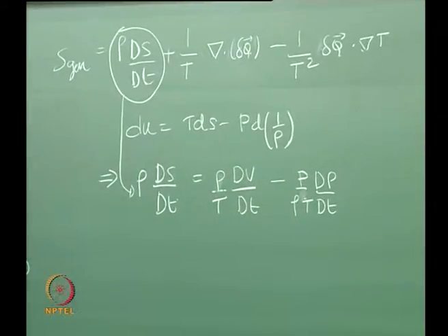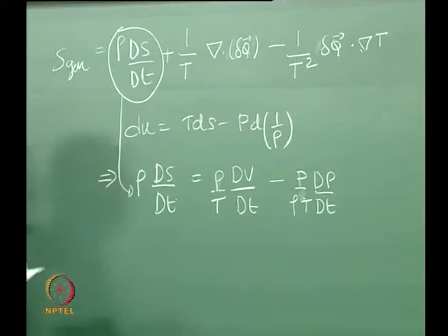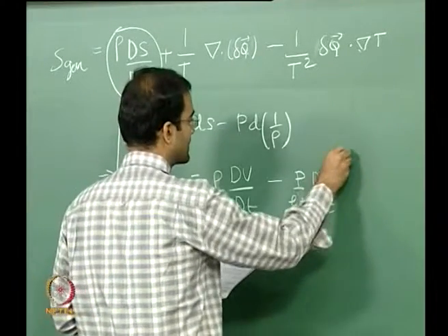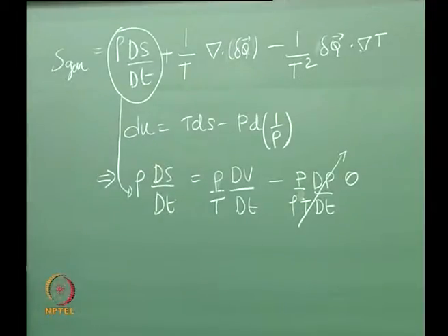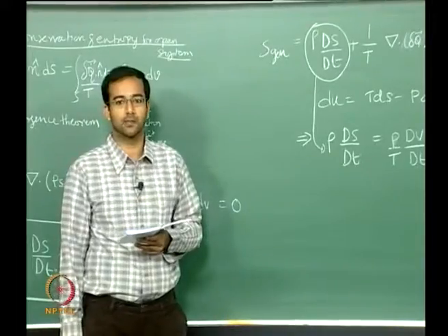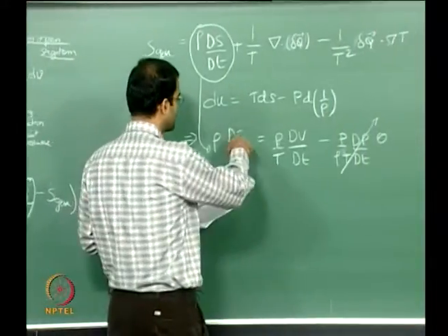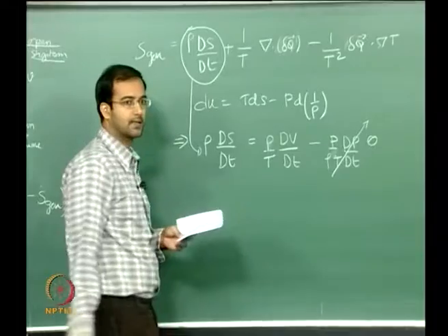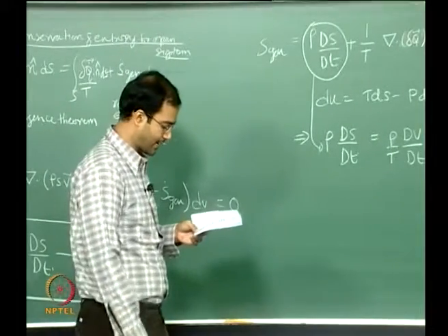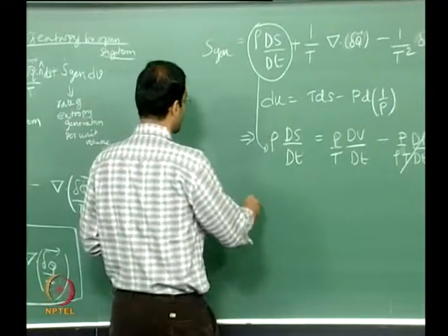Now if you look at incompressible flows, for that this has to be 0, right? So there is no change in density with respect to time, therefore the change in the entropy has to be directly the change in the internal energy of the system, that is directly linked there. So let us also express the first law now.